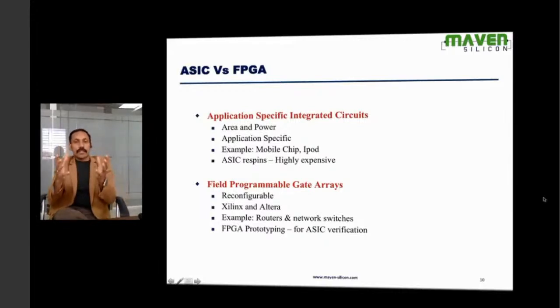After creating the architecture, you have to look at how best you can verify the source code. And we have to find the bugs as much as possible during the simulation phase. If you leave any bugs, later on, it would be more expensive. That's called ASIC respin. So what we do is sometimes we think how we can use FPGAs to verify ASIC.